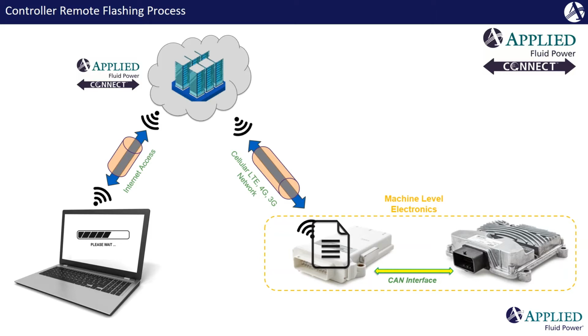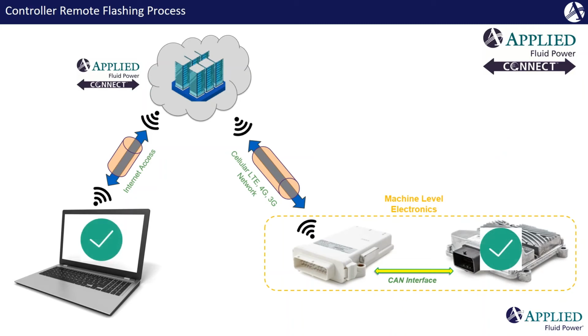So if you go ahead and upload that file and because of a poor internet connection it takes a while, that's okay. It's CRC redundant checked to make sure that we don't have to establish a continual link during this process. Each stage is checked. So from there, through the CAN interface, that program is flashed to the ECU.